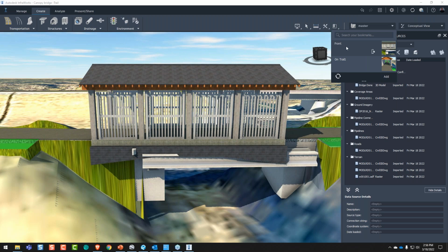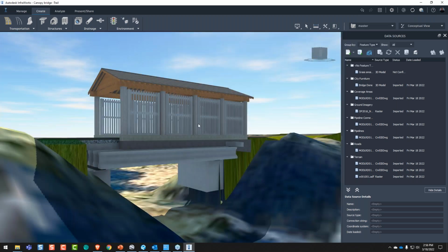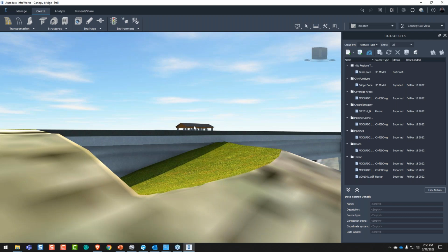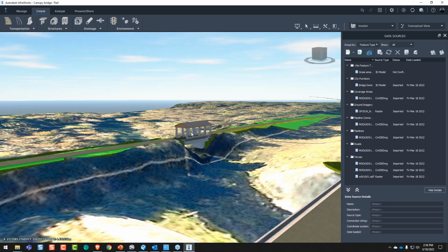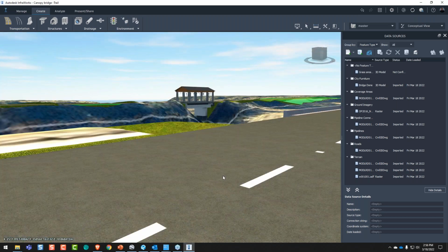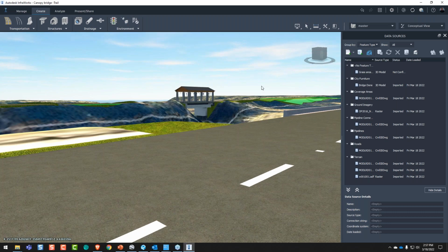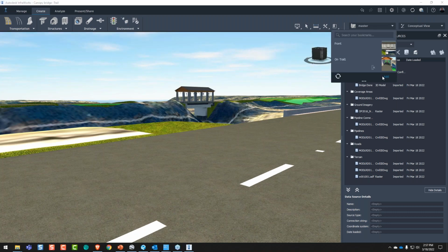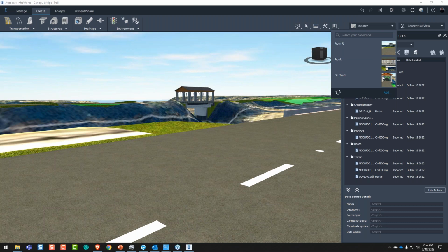All right, see how easy this is? It's not hard at all, right? I could do it here too if I want to see it from the road, maybe. You want to see it from the road. So I'll pan down here like so, right? Bookmark, add, from road, enter. Right, pretty straightforward. And of course here I can click on these, right? See how easy that is.